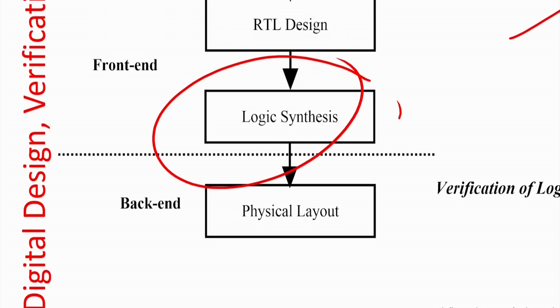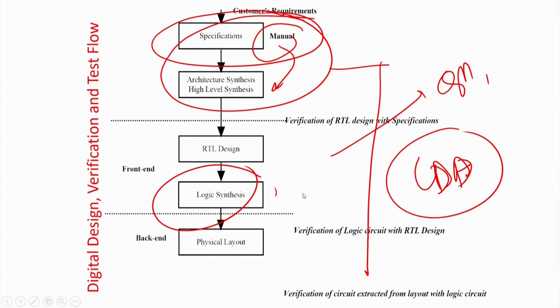So we will be having good algorithms so that you can synthesize a very good quality circuit and also in a very fast amount of time, because Quine-McCluskey and the Karnaugh map can also solve the problem, but they will take years to design a circuit, while heuristics like Espresso will do it in a click, in a very short amount of time. Then finally there is something called physical layout. Physical layout means the gate level will be implemented in terms of hardware,